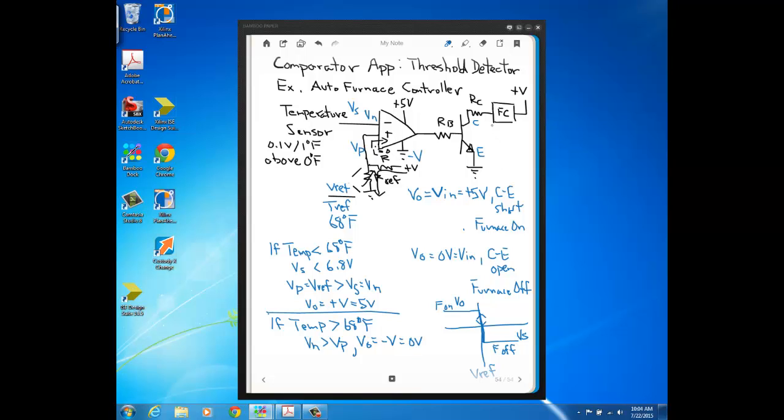During the time that they're flickering, that's what you're seeing. You're seeing the output of a comparator circuit like this at the unstable point. That's the flickering, as the output goes on and off, and current flows through the lamp and then doesn't. And in that application, you don't care that the lights flicker a little bit before they come on and stay on. So a comparator would be fine for that application. But in applications where that instability at V0, due to the inputs being close together in value, is a problem, there's something you can do, and that something's called a Schmitt trigger, which we're going to talk about in the next video.